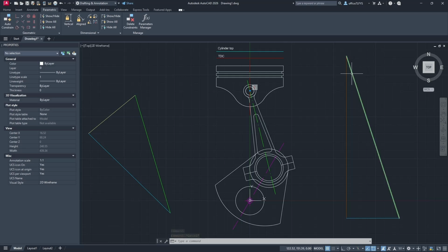So it's essential first to set the geometrical constraints, and these three pairs must be coincident. This top point must be fixed so that the diagram is positioned downward from this location. Choose Fix. This component must always be vertical. We will choose Vertical and select the object.